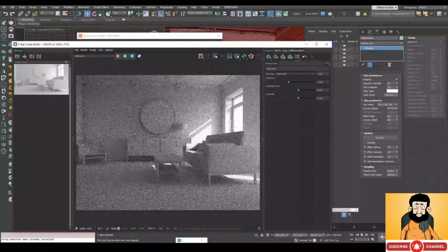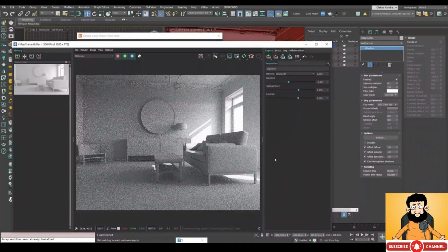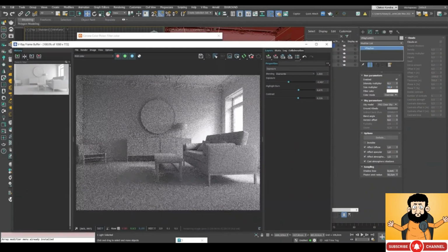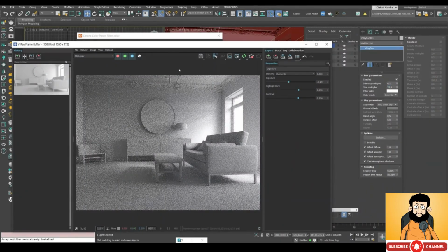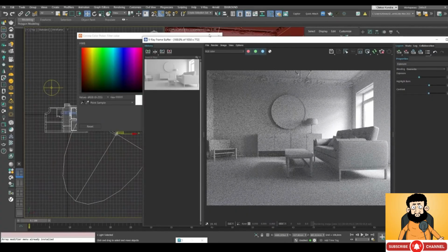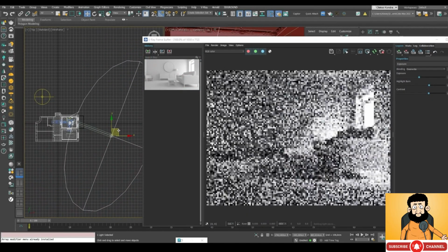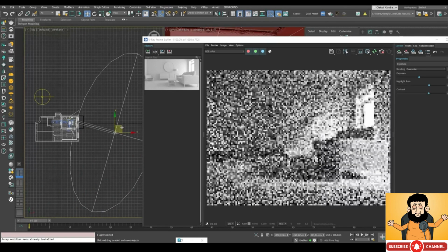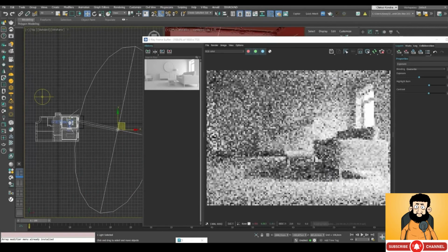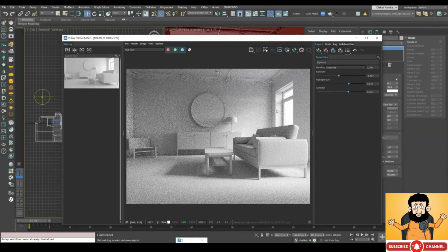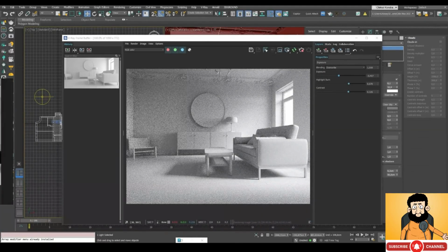Filter color is white, and then we change size multiplier to 32 to get blurry sunlight. We can direct the beam of sunlight through the windows, illuminating the areas that we want. The floor, for example. So we've achieved a neutral kind of light.